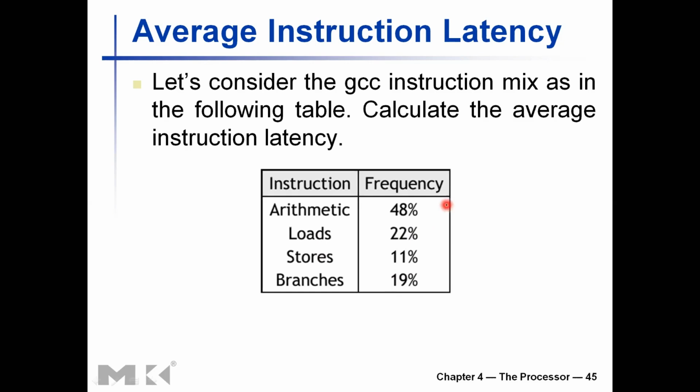So if we try to compute the time taken by our single cycle implementation, then we have to apply the 7 nanosecond time per instruction for all these types of instructions. But in reality, if we can complete each instruction by only the time it needs, then you can compute a weighted sum.